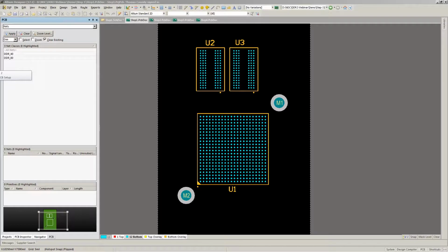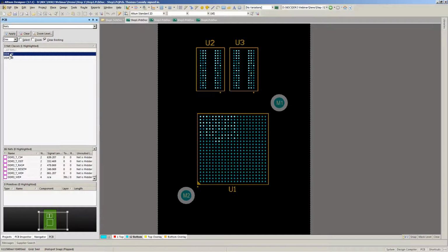And then if you want to, at this stage, you can also define several net classes. Altium uses these to help you set up net class rules, routing rules. So at this stage, really all you need is just single and differential. So these are all the single layers, single signals, and these are the differential signals.